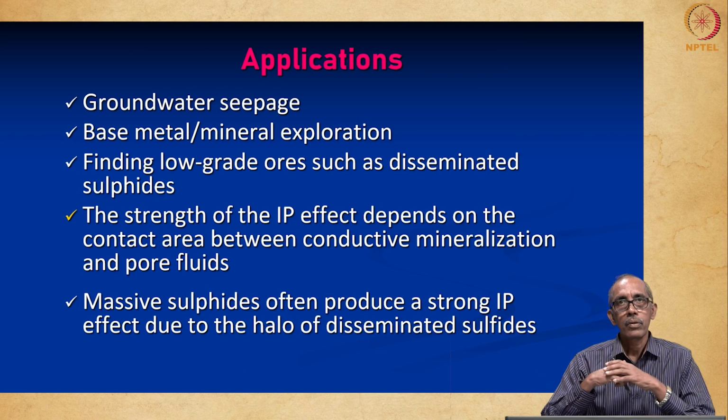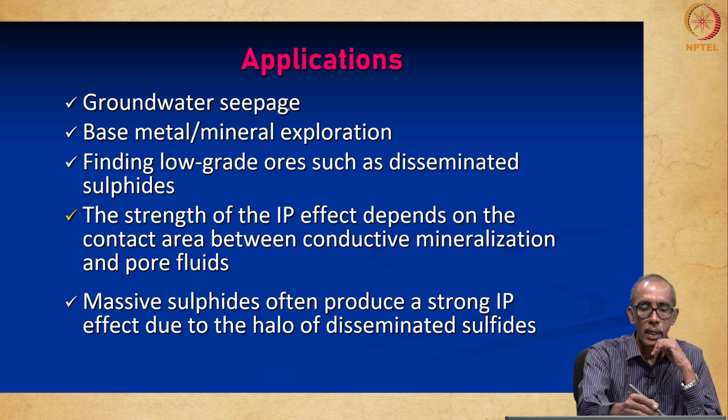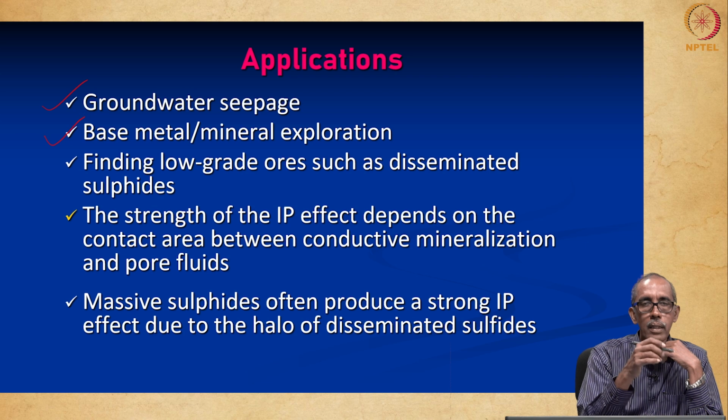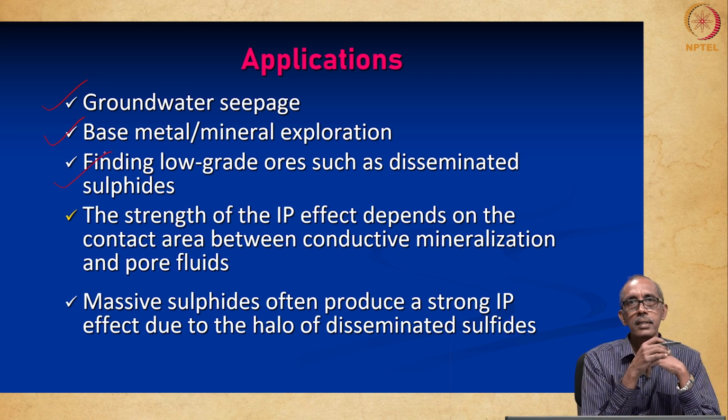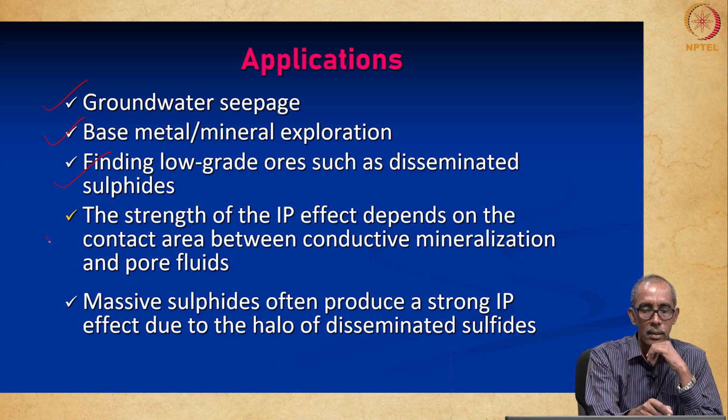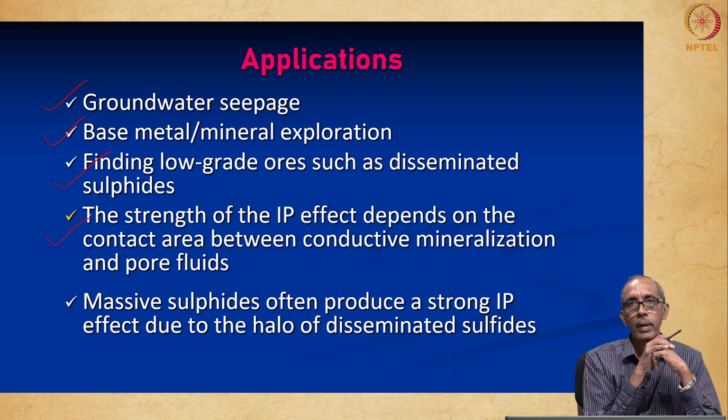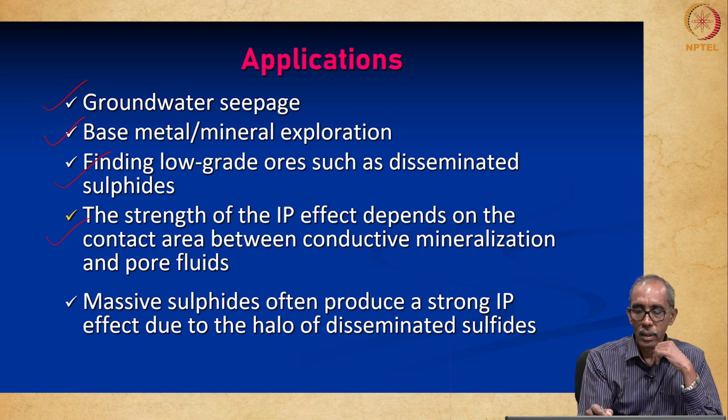Now, coming to the applications part, these are the broad applications: mainly in groundwater investigations, obviously in mineral exploration, and also for understanding sulfide ores, because sulfides have a capacity to remain polarized for a longer time, right. The strength of the IP effect depends on the conductive mineralization and the pore fluids.